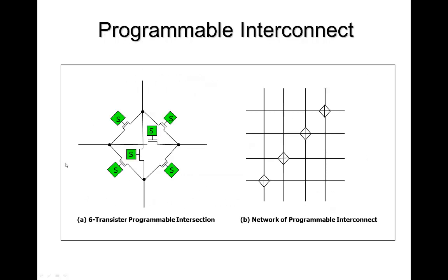So how do we have this flexible routing architecture? Well, we use this diagram showing N transistors, but it could be transmission gates as well, with a P transistor in parallel. Here we have a set of wires, and at this junction we have all these transistors. If this transistor is on, by putting a 1 in this memory bit, then this allows us to go around the corner this way. Likewise, if this was also 1, we could go around the corner this way. Or we could go straight through, or we could have a broadcast. So it's a pretty reconfigurable way of creating a network. You'd have a whole mess of wires on your chip, and each of these intersections will have 6 transistors at minimum.